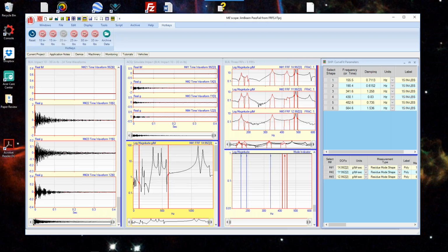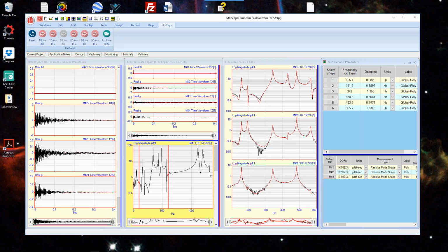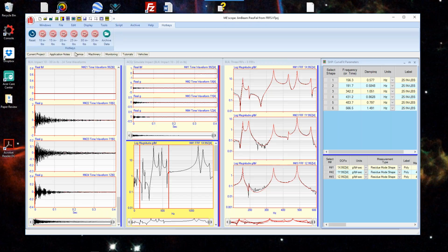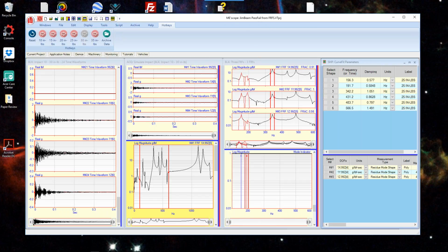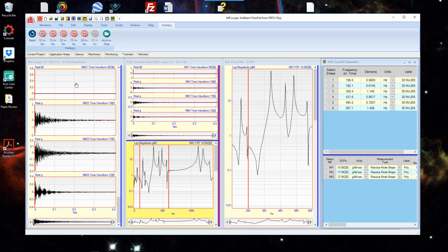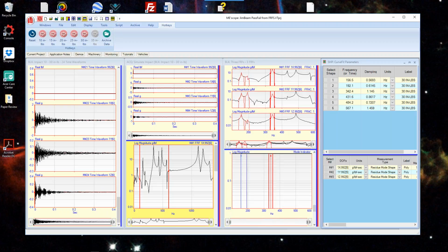So it's now curve fitting that data. And you can see 565.7. So the frequencies are going up as I apply more torque, which is something that we know from modal analysis, well known that resonances are a function of the physical properties of the structure. So as I increase the stiffness between the top plate and the back plate, the frequencies increase ever so slightly.